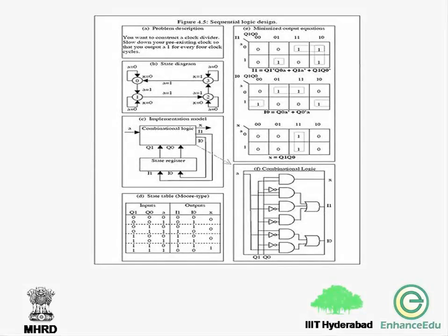Although a shift register stores n bits, they cannot be stored in parallel. Rather, they have to be shifted into the register serially, that is, 1 bit per clock edge. A counter is a register which can be incremented, that is, add binary 1 to its stored binary value. A counter has a clear input in its basic form. This resets all the stored bits to 0. It also has a count input that supports incrementing on the clock edge. Hence, the counter can count the number of ones that are coming to the input.